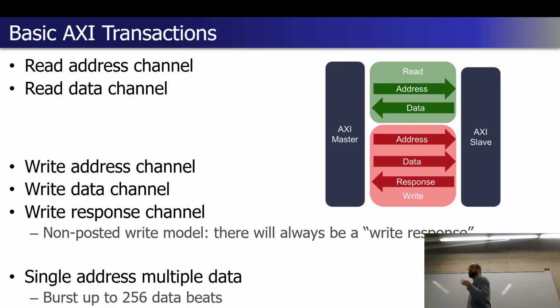But then the amount of things we can read or the amount of things we can write in the write channels that we have here can be more than just a single value at a time. So there's still the overhead, but it's somewhat amortized by that. You do the initial setup, and then you have multiple beats of data being sent over either the data read or write data ports.